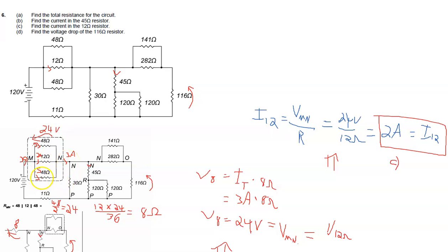And so remember now that the 24 volts across there, 24 over 48 confirms that calculation, right? And so the 3 amps divides into 3 currents, recombines into 3 amps. This 3 amps now divides, a current goes that way, a current goes that way. I don't know if we calculated either one of them, but we calculated this one, and they add up to this one. And so Kirchhoff's current law and Kirchhoff's voltage law apply across all that.